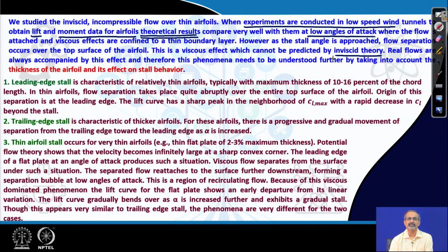We saw that the CL curve extends perpetually to large angles of attack remaining linear, which means it misses out the stall phenomenon altogether. So, that is where we have to look at actual experimental data to see the viscous effects having an impact on the aerodynamic response. There could be thickness variation in airfoils, and we need to look at the effect on stall behavior.